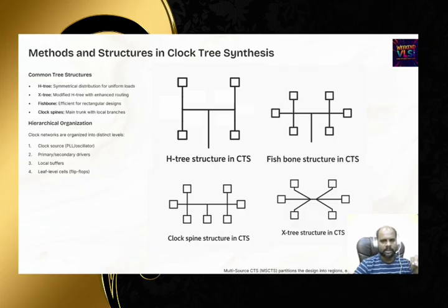Advantage, better skew control and good delay balancing. Okay, what is the disadvantage? The wire length is higher, similar to whatever we saw in the clock spine. Here also, the wire length and power will be high.